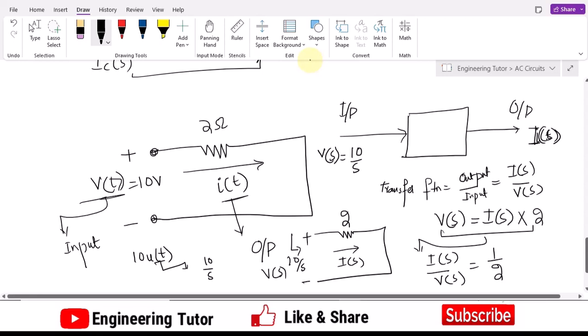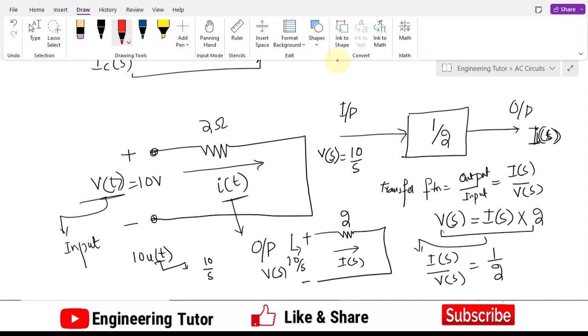Now, writing it here, when the input of 10 by S is applied, the output will be multiplied with this term. Here we get 10 by S multiplied by 1 by 2, which gives 5 by S. That is the I of S.